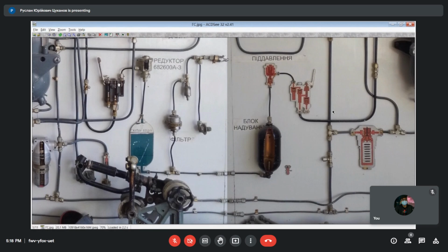And this overpressure should not exceed limits, otherwise the hydraulic tank will be overloaded and can be destroyed by this overpressure. So when the airplane climbs to high altitude, ambient pressure drops, so overpressure from the tank must be released. This is the primary function of this pressure relief valve.